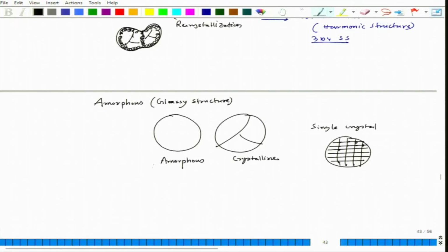When we come to amorphous and crystalline, we tend to see a very good corrosion resistance in amorphous because it does not have crystalline boundaries, or grain boundaries. Now the major thing is this would show high corrosion resistance, fine, compared to crystalline. So this will show poor corrosion resistance. This is a general consensus.